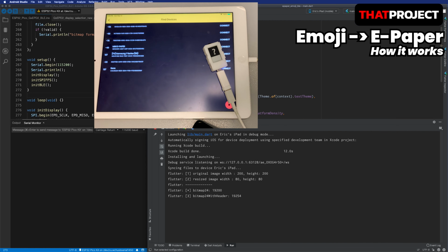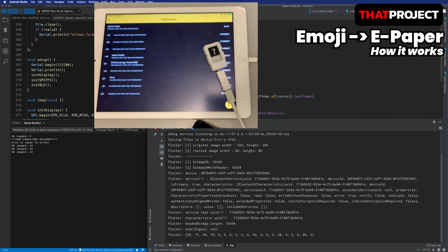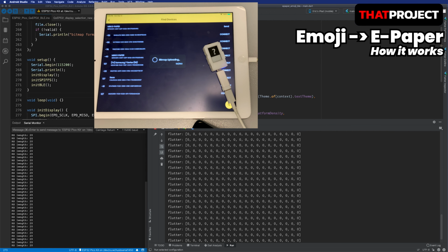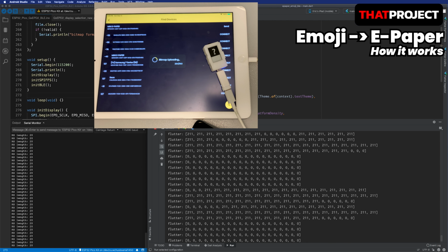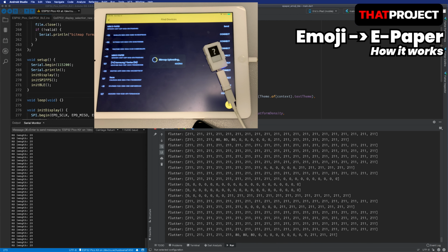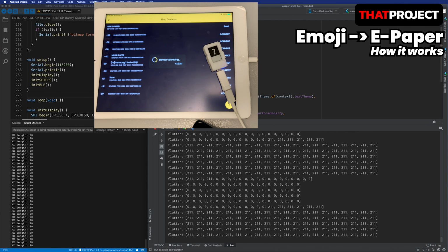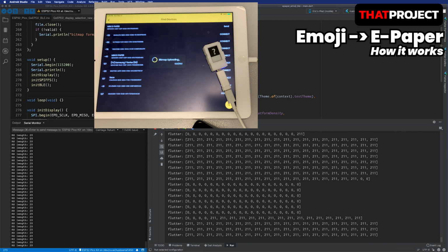Unfortunately, the bitmap supported by the Epaper display library GxEPD2 is up to 24 bits. So it was necessary to change the 32-bit bitmap to 24 bits. Please refer to my code for this part if you need more detail. In fact, a 1-bit image is enough for this project. This is because only white and black can be printed on the display. I'm using this part for other projects, but I will update it when I have a chance.